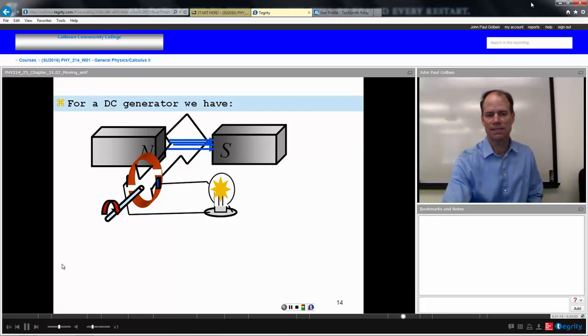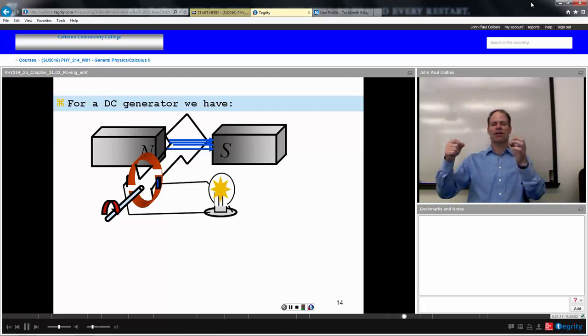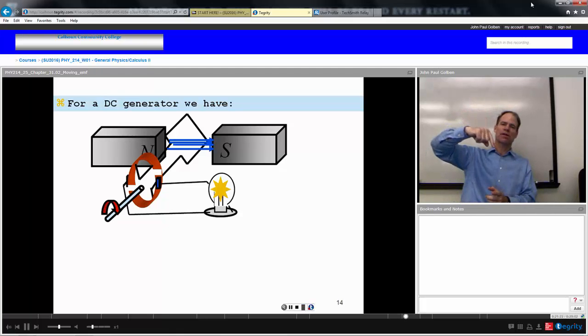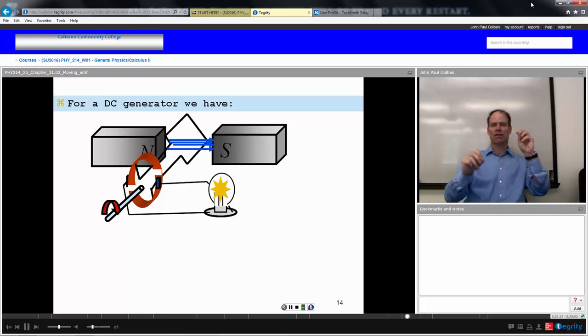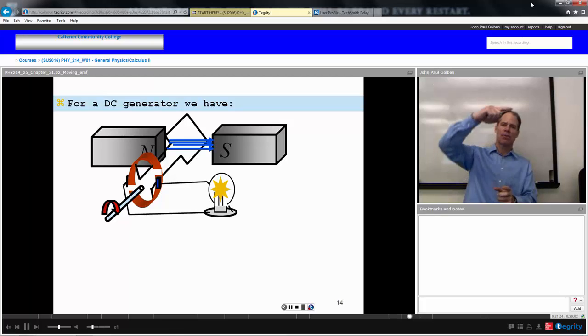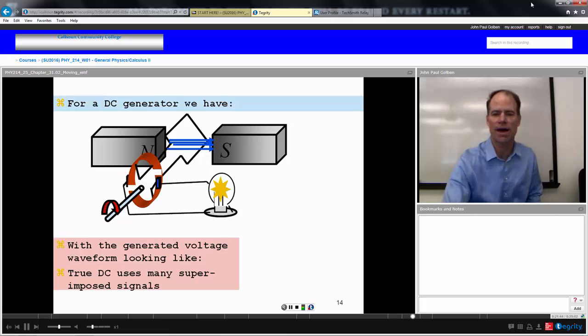If we want a DC generator, we might put two gaps in our contacts there. So as we're going positive with our sinusoidal function, we're just about to go negative, then we reverse the leads by going over those gaps, and both leads will change, and hence what was going to be negative all of a sudden becomes positive again. Then as we're about to go negative again, we reverse the leads again by the action of those two gaps, and then it goes positive again. So we rectify everything in a positive way, so it looks something like this.